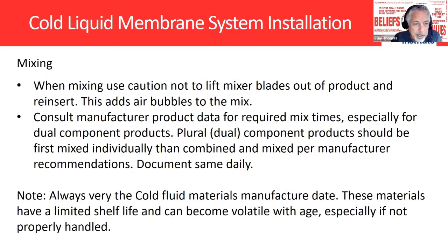Again, mixing, you don't want to get air in your mix. And another thing with these products, very specific as to manufacture date and shelf life. You want to be cautious that you're not using products that are out of date. In fact, some of these products, when they get old and sit on the shelf too long, they become volatile, which means I've seen the lids fly off the cans all by themselves sitting on the shelf, when they get hot, if you store them too close to the ceiling in the warehouse. So you need to make sure that any of these products you're using are not expired.